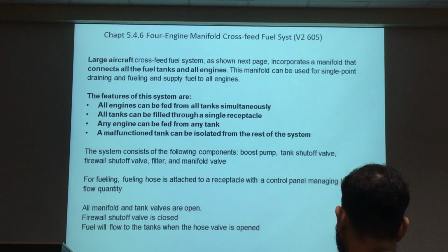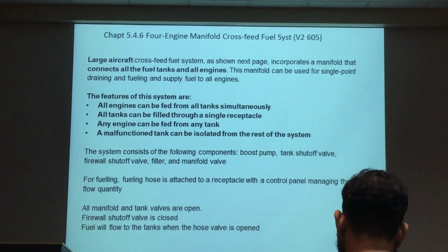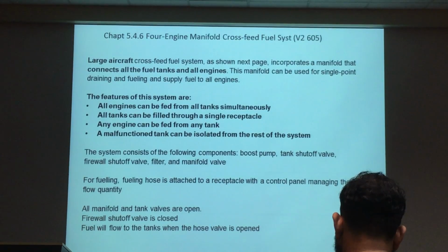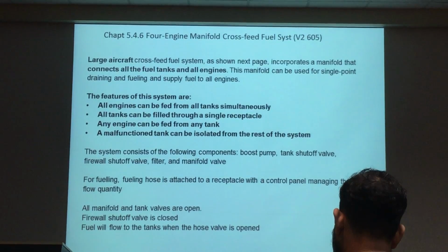Okay, any engine can be fed by any tank. This is the requirement. A malfunctioning tank: let's say one tank, the pump is not working or the line is broken. The fuel line inside the tank is broken. Okay? The fuel cannot be pumped out. So you must isolate this tank. Able to cut it off. Yeah, this is called isolation.